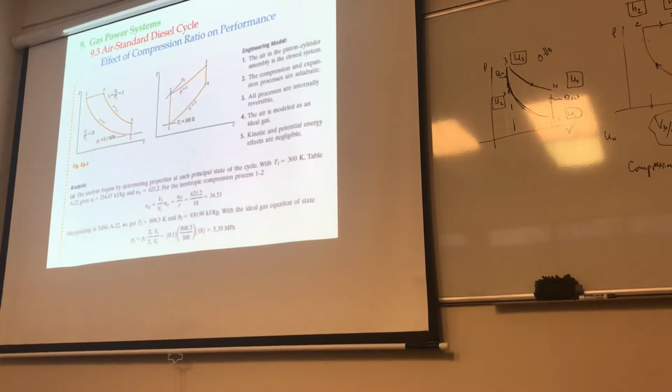Then you look at that table and try to find the state that gives you VR2 equals 3451. In most cases, you have to do a little interpolation. As you do that, it gives you immediately the temperature, and in this case, it's not U2 that I want, but I want H2. So you just read the column over, right? So you read T2 and H2.